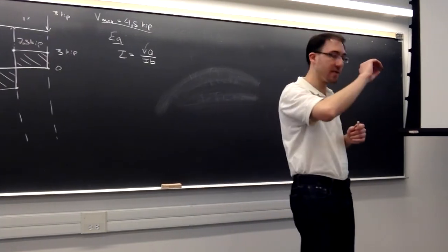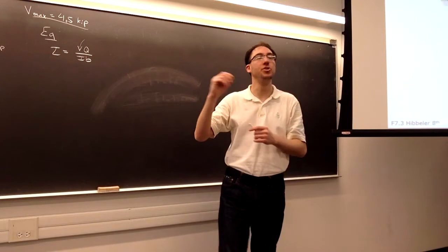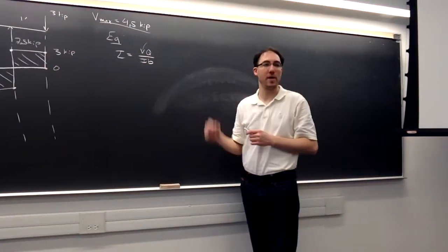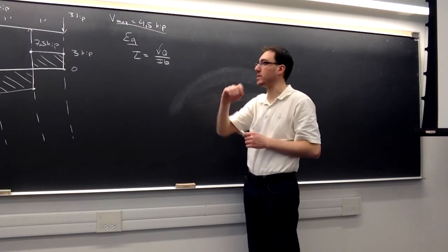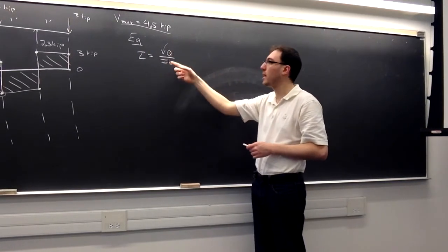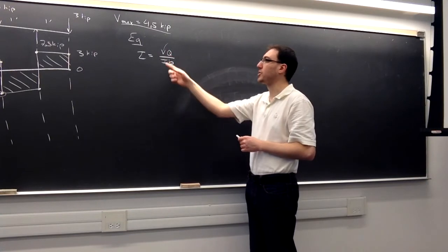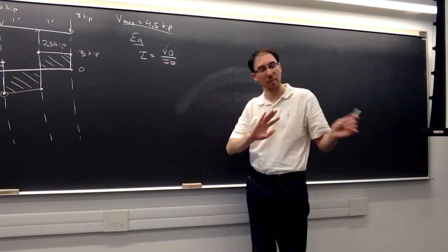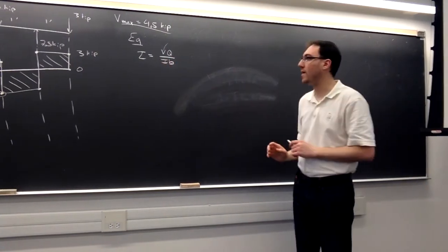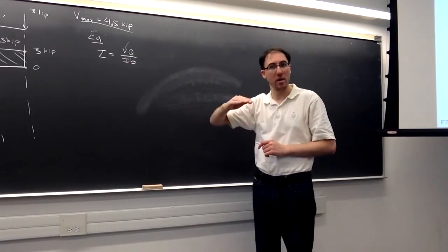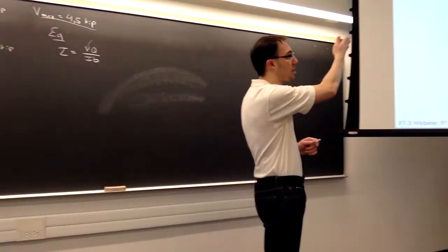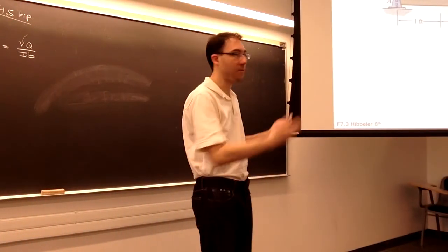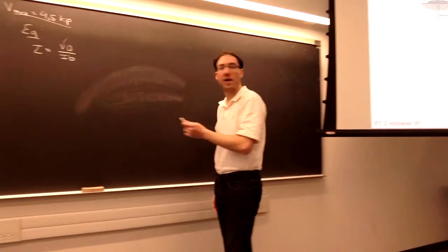Right, specifically the neutral axis is usually where my shear stress is going to be maximum. So the location in the y direction dictates what I'll use for Q and what I'll use for B. But actually, I will be independent of that. So let's take a step back. We can find I without knowing where along the cross-section we want to find the stress, because the cross-section doesn't change from 2 feet to 3 feet. So let's find the value of I.